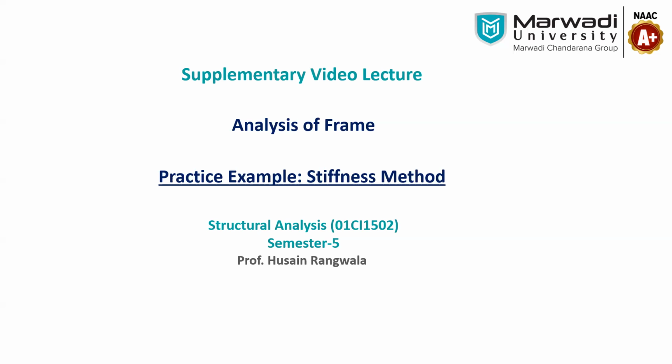What is the difference between the non-sway and sway frame? Basically both are frames only, but in the sway frame, there is an additional unknown we have to consider, that is the lateral deflection. If you compare with the previous example, when we neglected the axial deformation, our unknown displacements were nothing but rotations. We did not consider the effect of any horizontal or vertical translations.